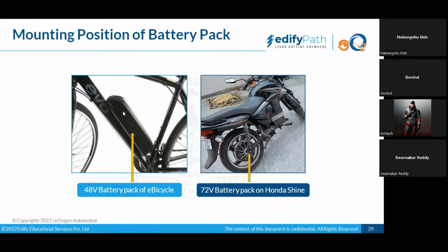We are trying to show you, in different frames on different bikes or scooties or cycles, how you have to make provisions in your chassis, so that initially you know where you are placing your battery, where your motor is, and what kind of motor it would be, either a hub motor or a mid-drive motor. After you have taken those decisions, your chassis should be designed accordingly, so that it could be assembled, or put into the bike.